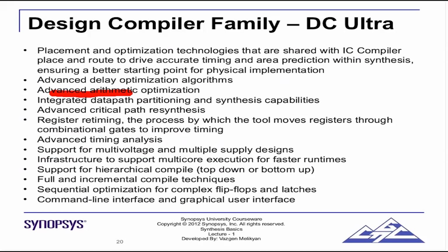It helps in critical path resynthesis and register retiming, which is a very important feature. It has capabilities for advanced timing analysis. So you see a lot of advanced here. It is just an advanced version of DC Expert. It is also capable of running big designs. It supports multi-core execution for faster runtime, which is very important for big designs. Rest of the things are the same as DC Expert.